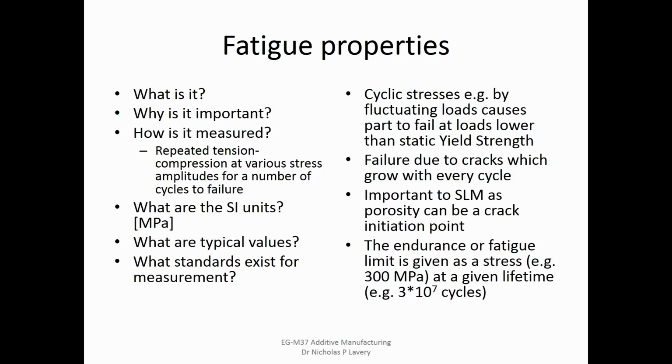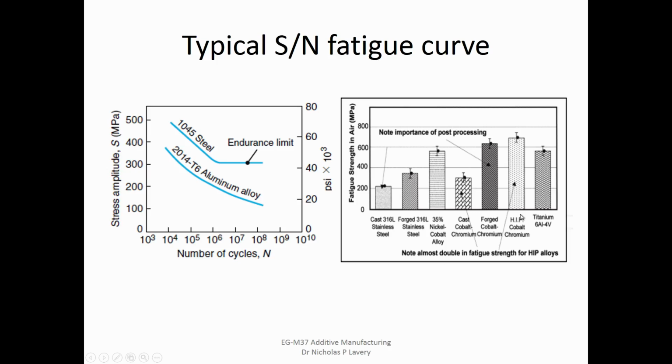Just to finish off with a final set of properties: fatigue. You know about fatigue a little bit. You put it in the machine, and you'll have high cycle fatigue and low cycle fatigue. It just depends on how many times you can put in different waveforms, and the amplitude of the waveforms. You're looking at some sort of repeated development of small cracks, which develop into bigger cracks, and the failure of the material. What you're ultimately interested in is how many cycles a particular material will undergo before it fails.